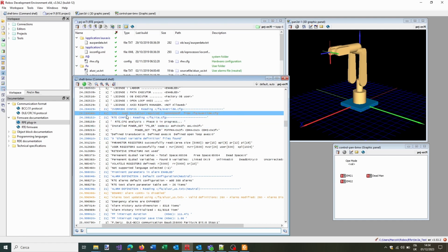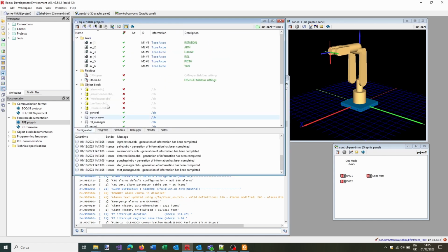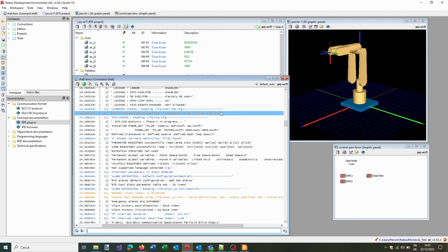we would like the axis required. You can see in this line, I take out the mouse because it's not reading so well. You can see the yellow written line, axis emulation required 0x3f. That's because I would like the emulation of all the 6 axes of my robot. You can see here 1, 2, 3, 4, 5, 6 axes in hexadecimal. The bit mask of this is 0x3f.